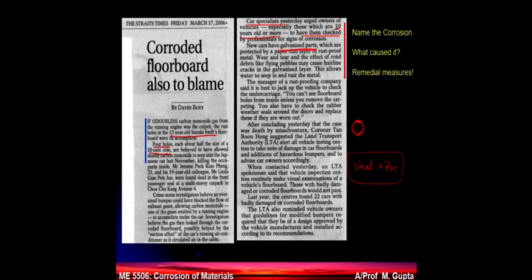They say that when you drive a car, you sometimes have pebbles, dust, and all these things, so they can come and damage this coating layer. You can have some cracks in here, and that leads to the corrosion, which is not correct. So don't take this news and opinion from people, because they are not corrosion experts. Even if there's a crack, as long as the zinc is there, it will protect the base metal. And if the damage is because of a crack, you will not get holes, you will get cracked areas. So that statement is wrong.